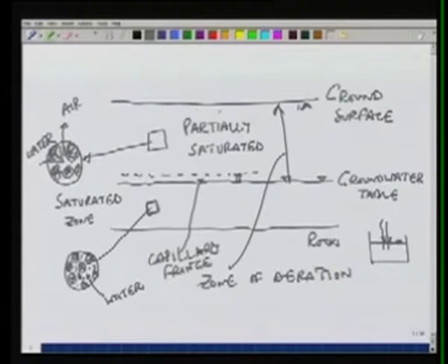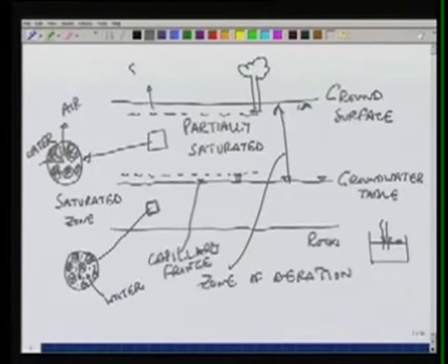If we go and look near the ground surface, there would be a zone just below the ground surface from which the plants can take water, and this is known as the soil water zone. The roots of the plants can take water from this zone, and this goes back into the atmosphere through transpiration. This zone is important more for an agriculture engineer, but from water sources point of view, we would be mostly concerned with the saturated zone or the groundwater.